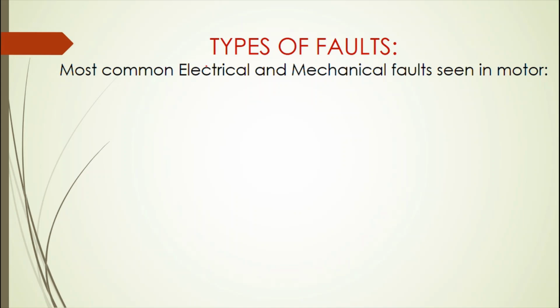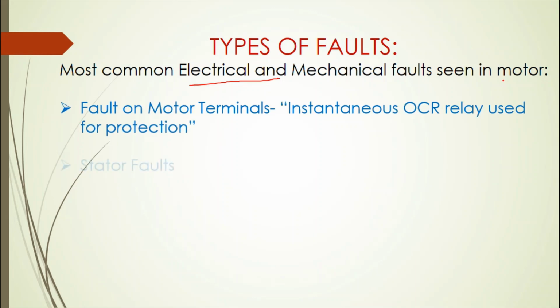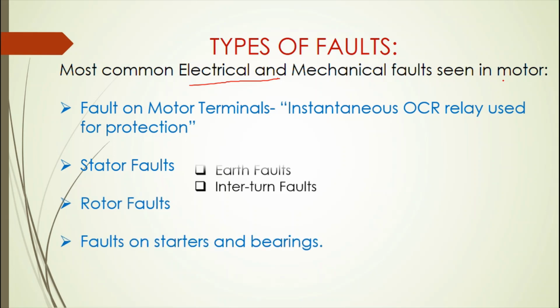Talking about the faults, the most common electrical and mechanical faults seen in a motor include fault on motor terminals, stator faults, rotor faults, and fault on starters and bearings. Fault on motor terminal. Such a fault produces a fault current which is even greater than the starting current. So, a fast and reliable operation is needed. For this purpose, instantaneous overcurrent relays are used for protection.